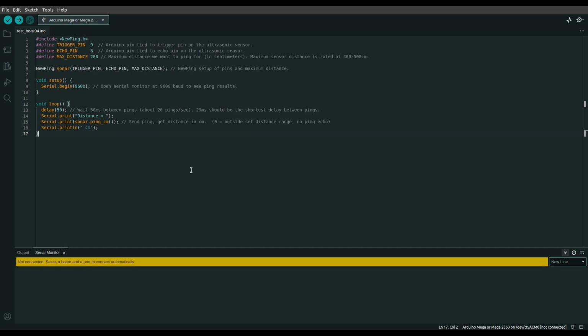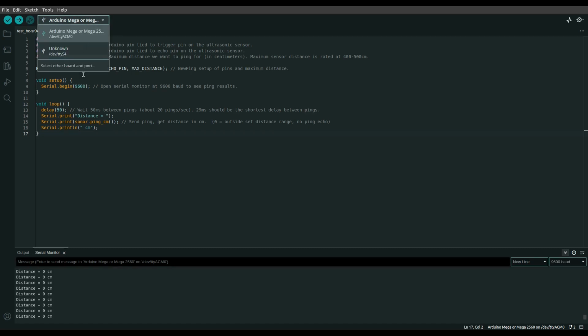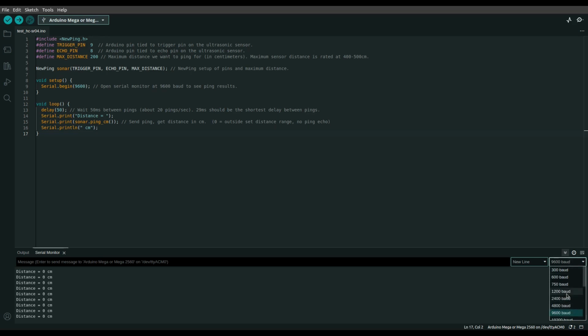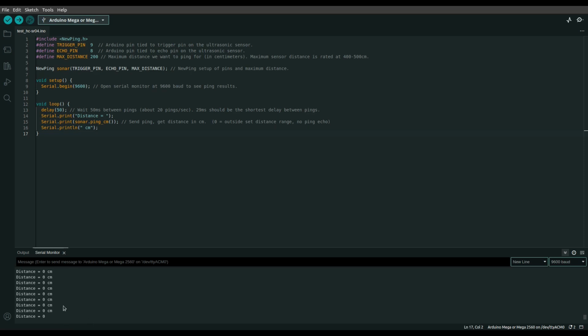Connect the Arduino to your computer. To test your code, you need to first click on the Verify button to check your code. Then click on the Upload button to upload your code to the Arduino board. Make sure you select the right Arduino board in the Arduino IDE. You can watch the serial port display for the results. Make sure you select the right baud rate. In our case, it's 9600. Finally, it's time to test your setup. Let's see it in action.